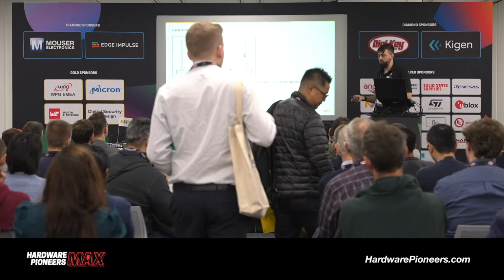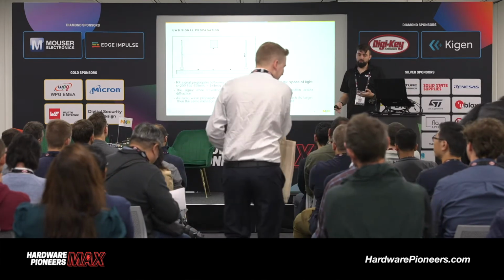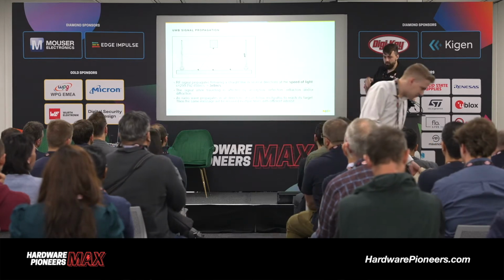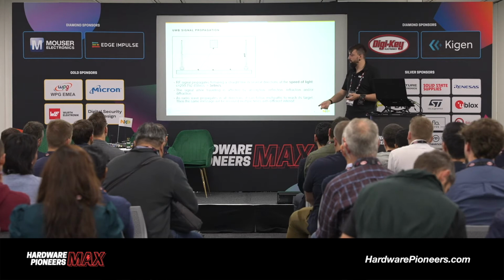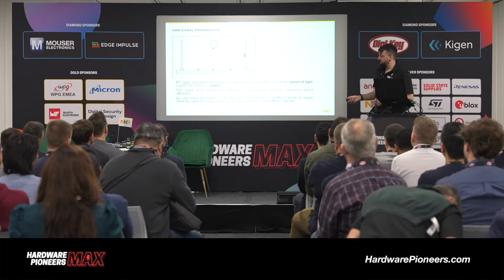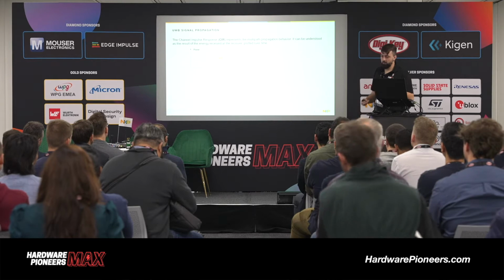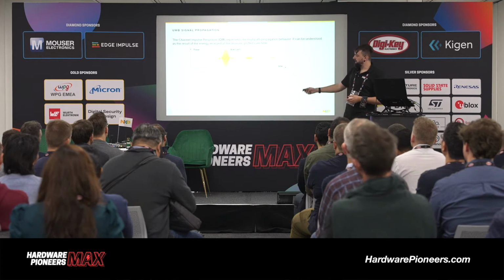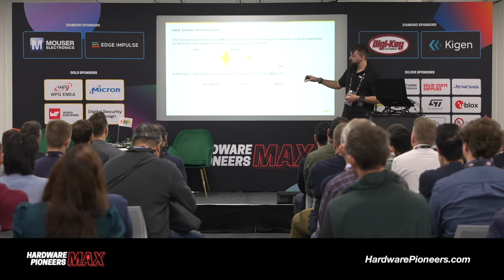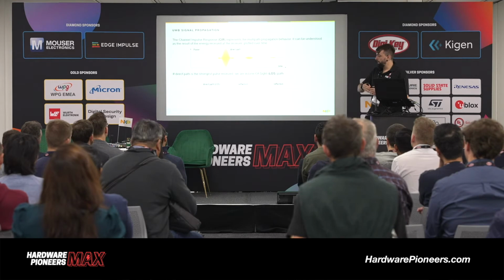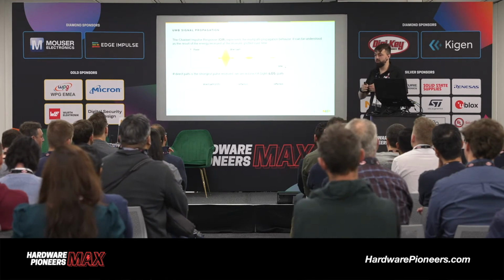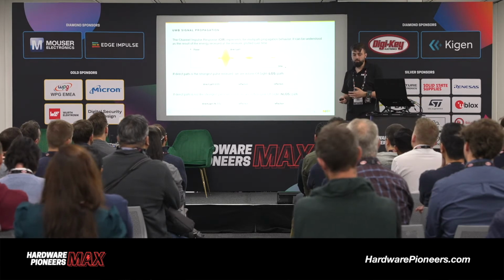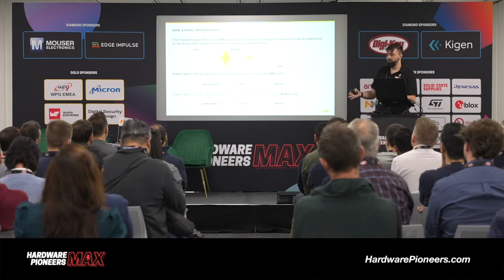This huge bandwidth and short signal improves its signal propagation, so that it can do direct path signals, of course. It can also be reflected off surfaces, but it also helps in signal propagation if you're not in a line of sight condition, because due to its nature, it can measure when the signal appears and when a reflection appears, and can discern between reflection and direct path. And this makes it much more robust in multipath environments.